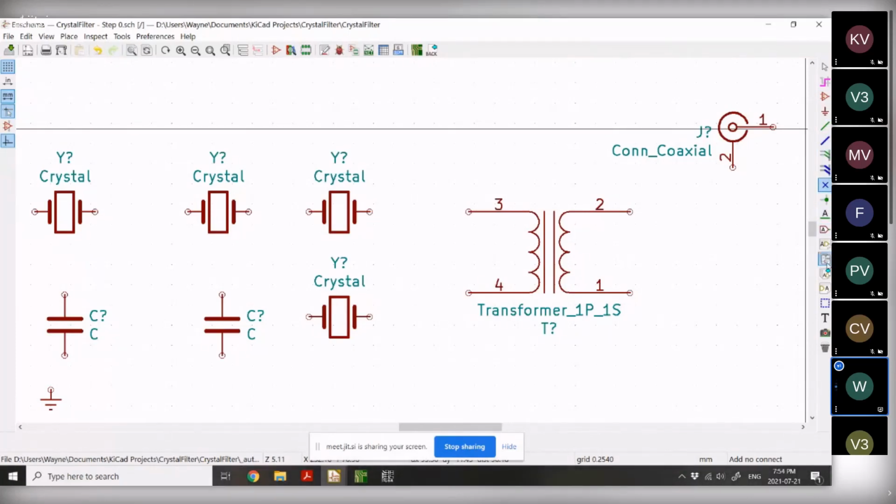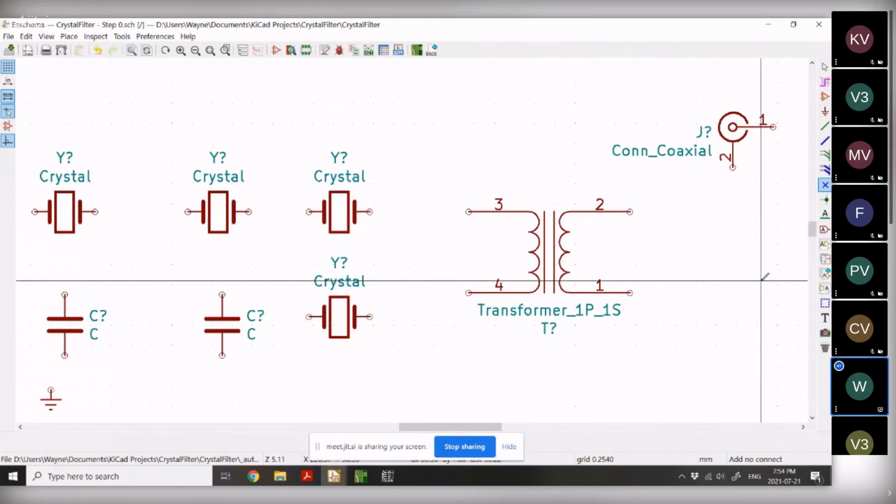Then there's a big section on subdiagrams if you want to use subdiagrams. I'm not going to show you that today. A reason you might want to use a subdiagram is what I just said. If you have a microcontroller, it's got a lot of pins on it. If you want to have a diagram that isn't too busy, you can drop the microcontroller and maybe the pins it's connected to, the sockets that you want it to connect to, the female or the male sockets. You can put those in a subdiagram.